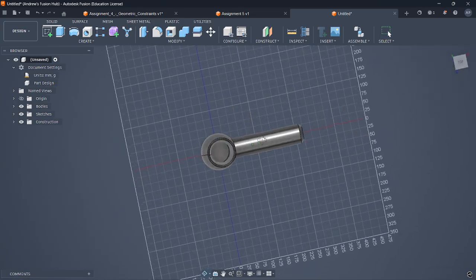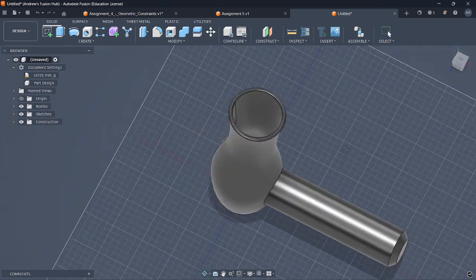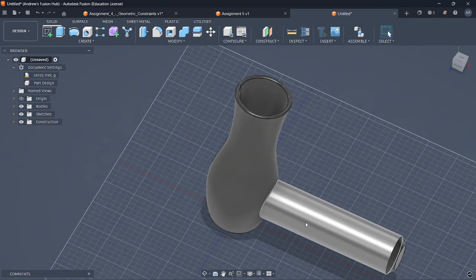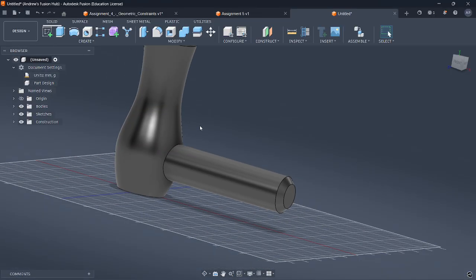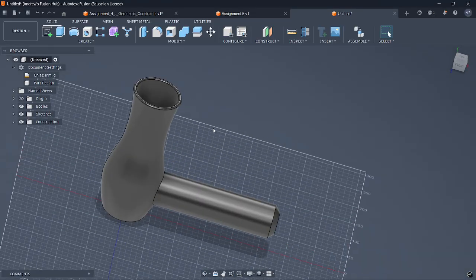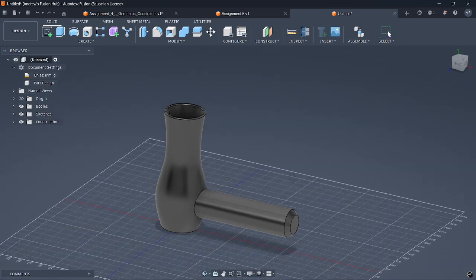So in this case, we have this hairdryer looking thing. This area is hollow, but let's just say I also wanted this area to be hollow as well, because we want to put electronics or whatever inside, right? I could cut something out, make another sketch, but in this case, I could also just utilize the shell feature that we created to shell not only the hairdryer head, but also the handle at the same time.